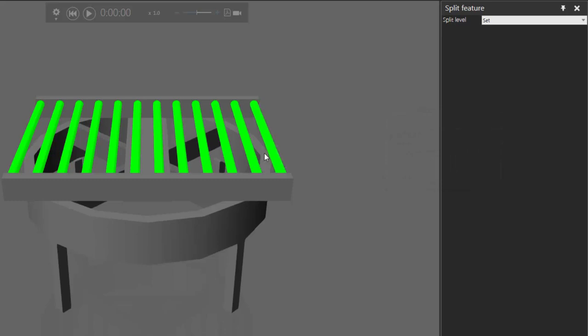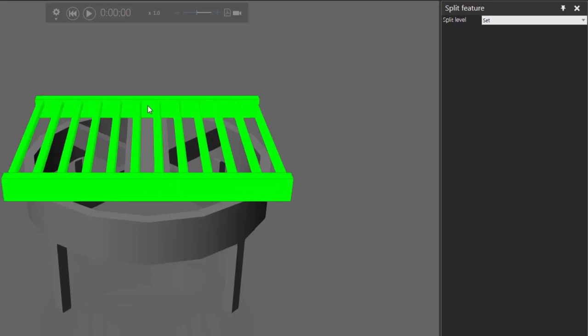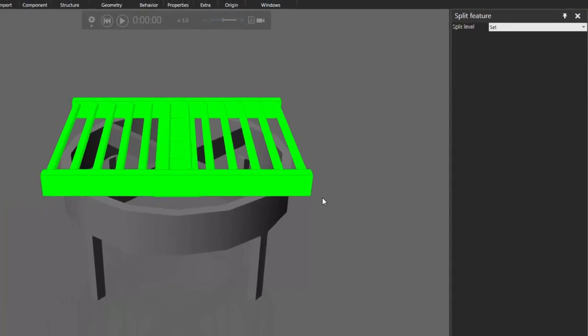There we go. Let's now select the side rails, so I'll hold down the Control key and click this side rail here to add it to the selection. And I'll click the other side rail here. I also want to add this plate that's supporting the table to my selection, so I'll click here on the plate. I actually selected this circle object here, but that's okay, we need that in our selection too. So I'll select the plate there, and this is all the geometry you should have selected. So now I want to move this geometry into a new feature.